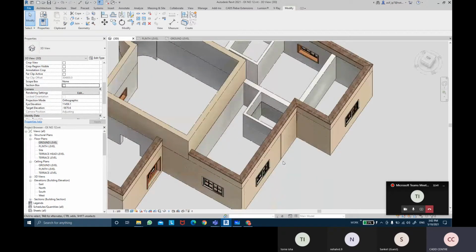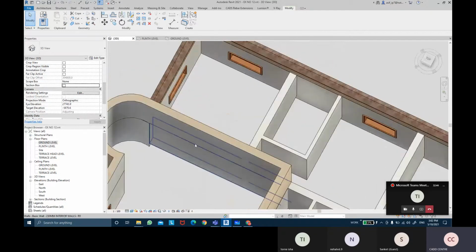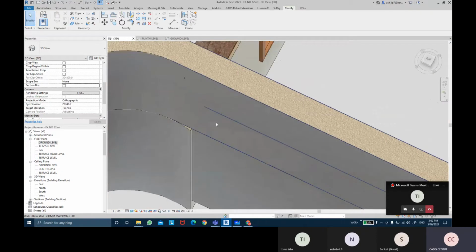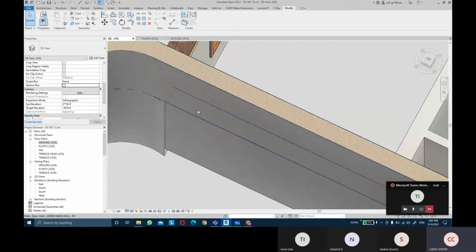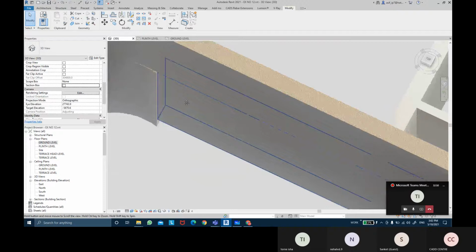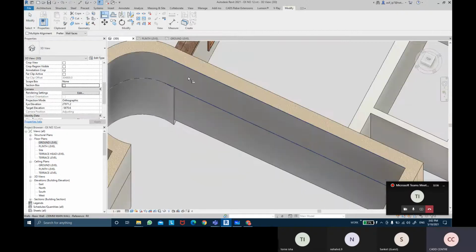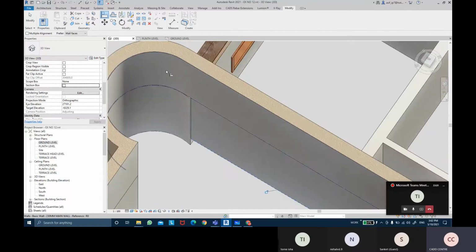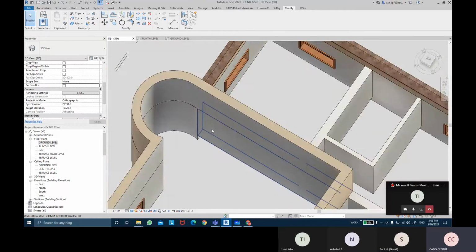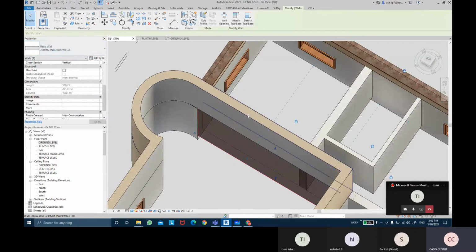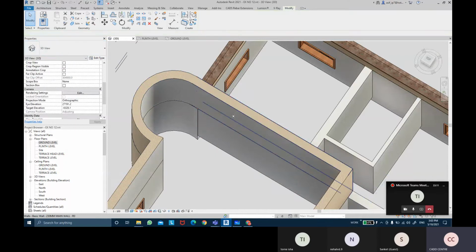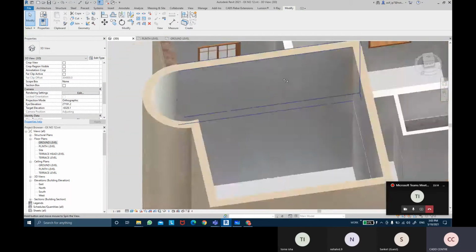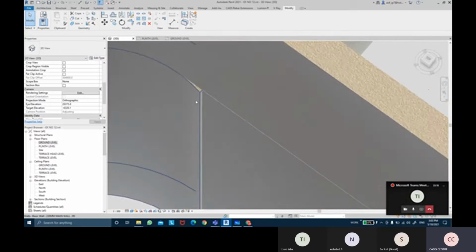The sunshade went away. Okay, we can fix that anyways. This portion of the wall is not aligned actually. We're going to say this face, top face, and this face, align it. So this type of wall is different. That's an interior type wall. This is the main wall. Yeah, so that makes the difference. So that's why it's not connecting.